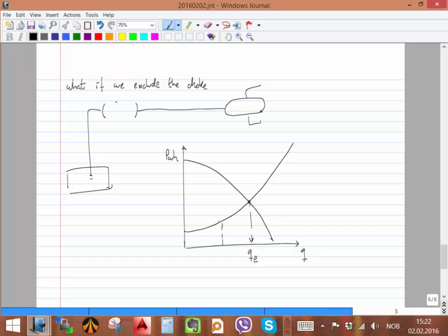You see the two pressures are quite different. I have more pressure than what I really need. So how can I bridge these two pressures? In that case, I have to produce a pressure drop that causes exactly this drop in pressure, this delta P. So that has to be the delta P of the choke.